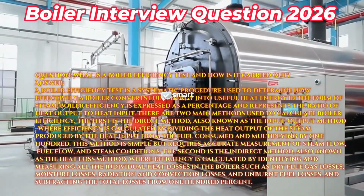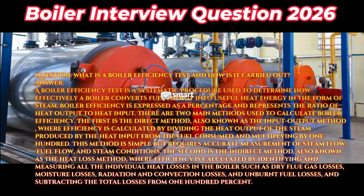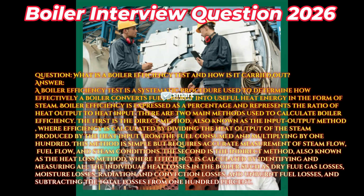Question: what is a boiler efficiency test and how is it carried out? Answer: a boiler efficiency test is a systematic procedure used to determine how effectively a boiler converts fuel energy into useful heat energy in the form of steam. Boiler efficiency is expressed as a percentage and represents the ratio of heat output to heat input. There are two main methods used to calculate boiler efficiency.